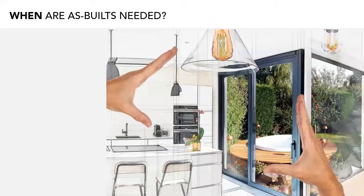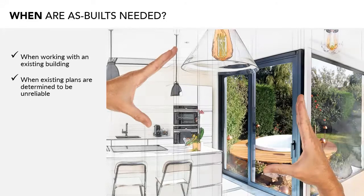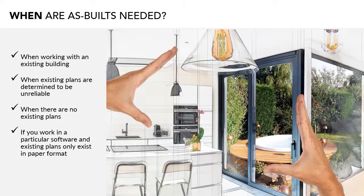So what are the contributing factors when as-builts are needed? Pretty much whenever we're working with an existing building, we need as-builts before starting design. And if the owner or client happens to already have as-built drawings, then we may just need to enter them into CAD or reformat them if they're already in CAD and confirm that the drawings are actually up to date. So if errors or inconsistencies are found, then at some point you may need a fresh set.